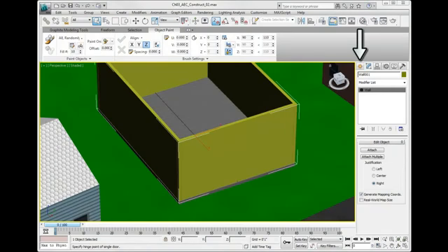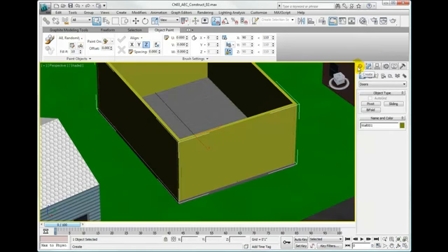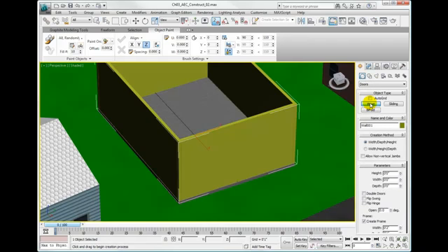In the Command panel, click on the Create tab. Make sure the Geometry option is selected. From the Geometry drop-down list, choose the Doors option. We're going to use a standard pivot door as the front door of our building. Click the Pivot option in the Object Type Rollout.